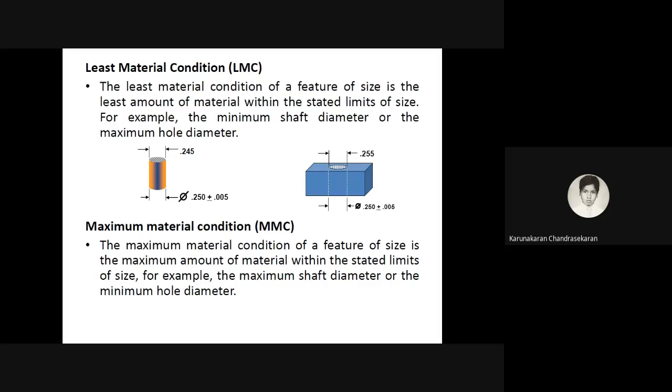Now, what type of dimension is mentioned? Is it metric dimensioning or inch dimensioning? Just by seeing, we can say it is inch type dimensioning. Okay, that starts lower and starts from 0.245 and so on. So now, in this tolerance, how much have they given? They have given plus or minus 0.05.